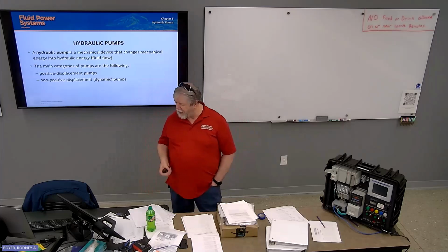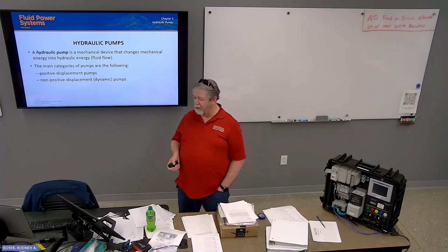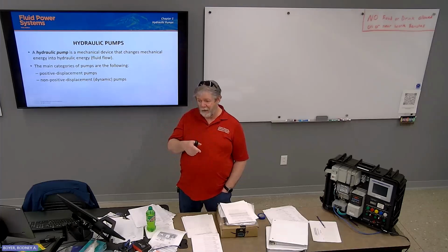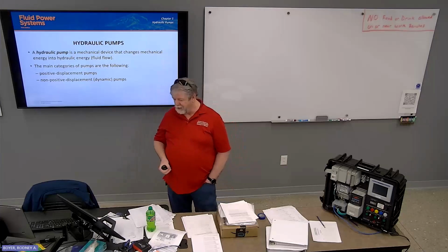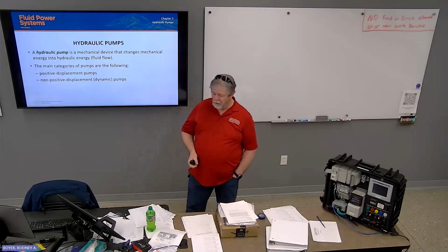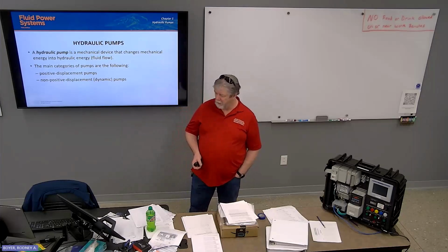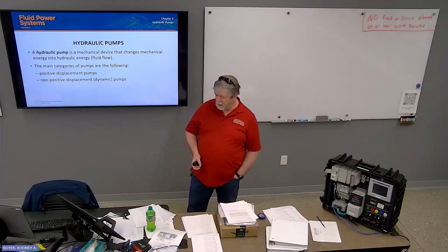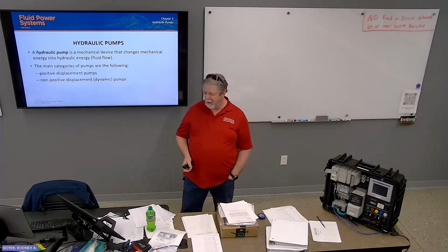A hydraulic pump is a mechanical device that changes mechanical energy into hydraulic energy, fluid flow. Actually it takes electrical energy, converts that into mechanical energy, and then that converts it into hydraulic energy. That's why the motor is called the prime mover, because if it doesn't work, nothing else does. Main categories of pumps are as follows: positive displacement and non-positive displacement. Pretty easy, yeah?